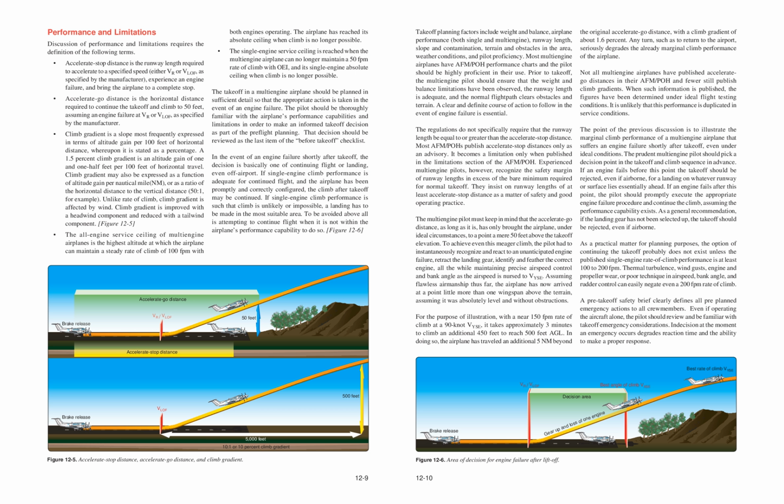A pre-takeoff safety brief clearly defines all pre-planned emergency actions to all crew members. Even if operating the aircraft alone, the pilot should review and be familiar with takeoff emergency considerations. Indecision at the moment an emergency occurs degrades reaction time and the ability to make a proper response.